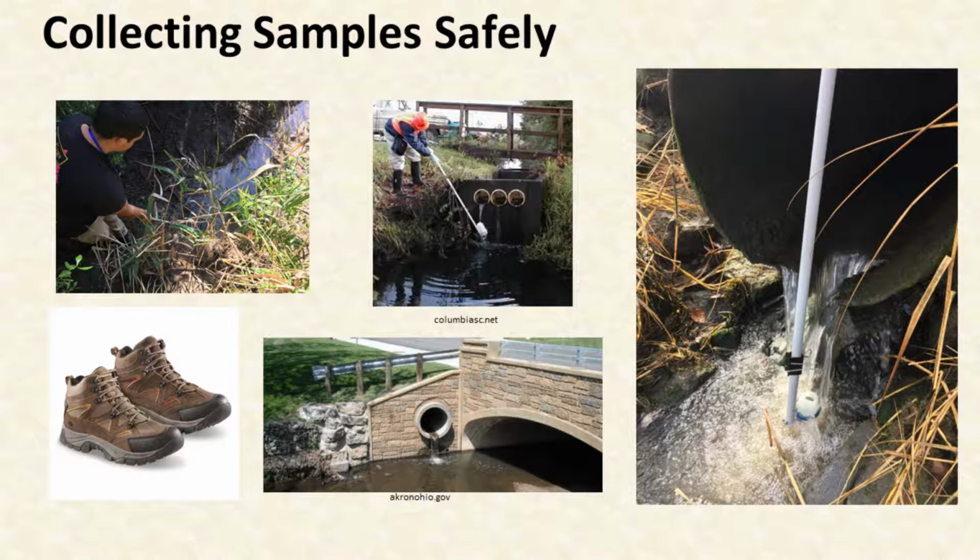The pole can also be used to extend outwards, allowing an individual to avoid thick brush, noxious plants, and unnecessary entry into waterways. Adjust the sample cup holder at the end of the pole to fit a variety of angles to collect a sample directly from a discharge pipe. This allows for successful sample collection while avoiding potential risks imposed by the outfall's immediate surroundings.